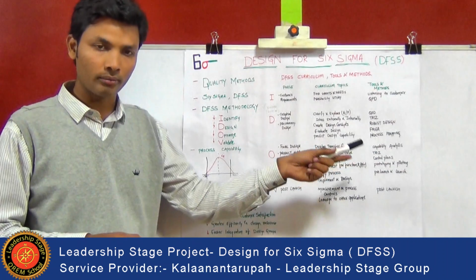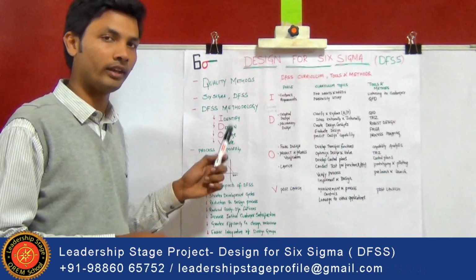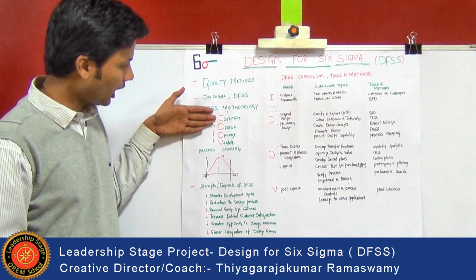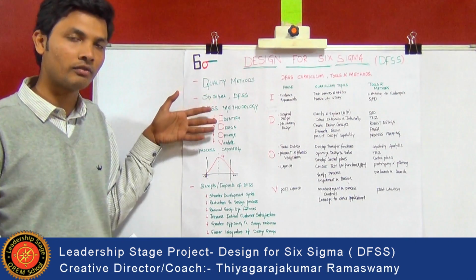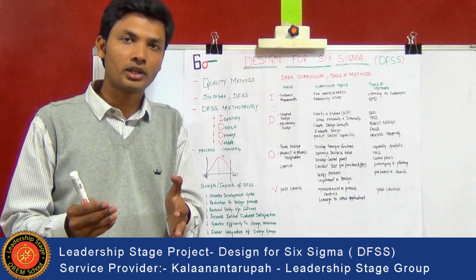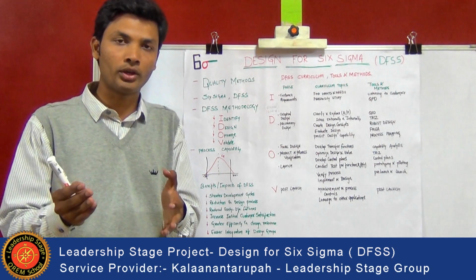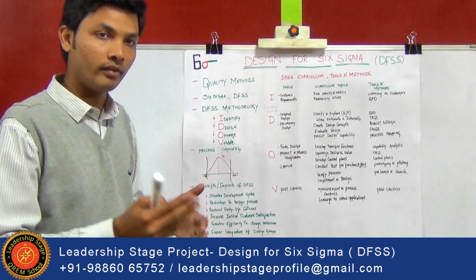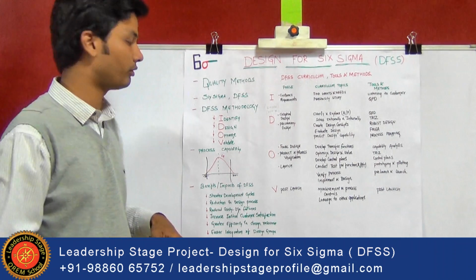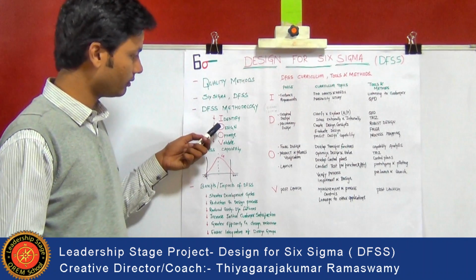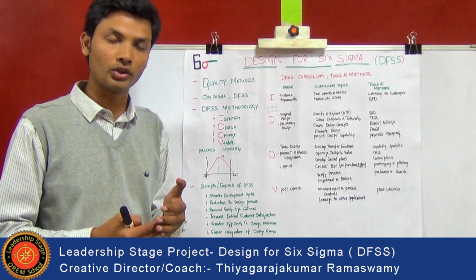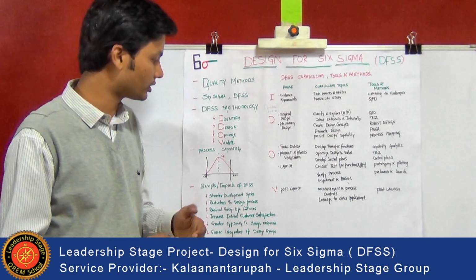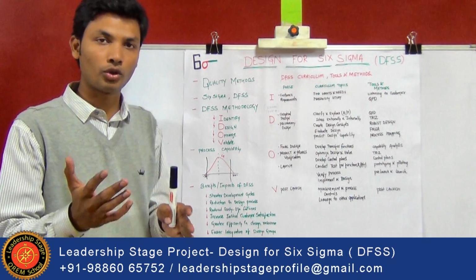Here I am going to give the whole brief description using the IDOV methodology. The DFSS methodology, as I explained, starts with identify. In the identify section, we find out the problems the customers have for the redesign of the component, or the applications for the customers for the new design of the component, and then we list them out by ranking them by priority. In the design, we generate the concept, design the component, do the testing of the load or the stress analysis, and then we do the control plans.